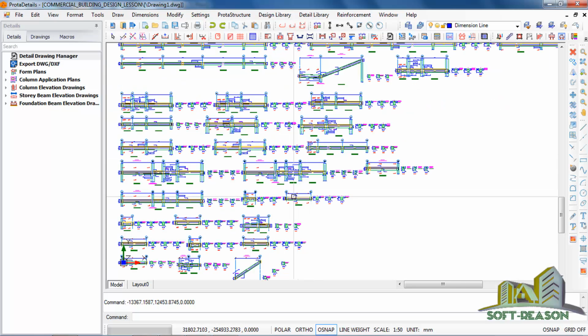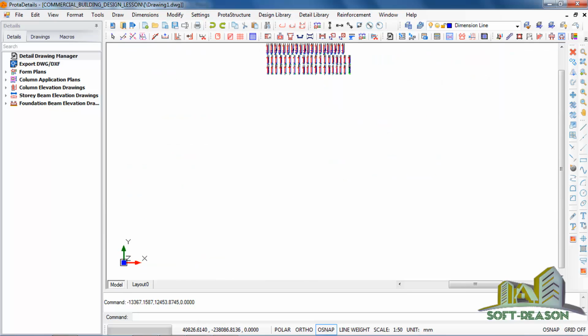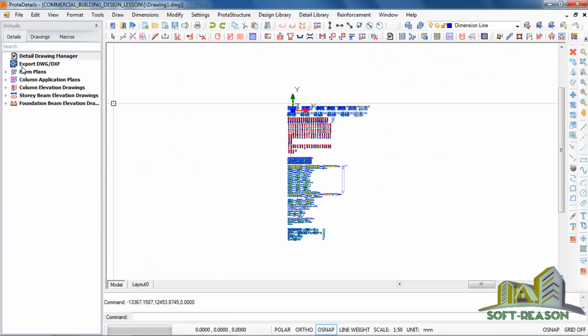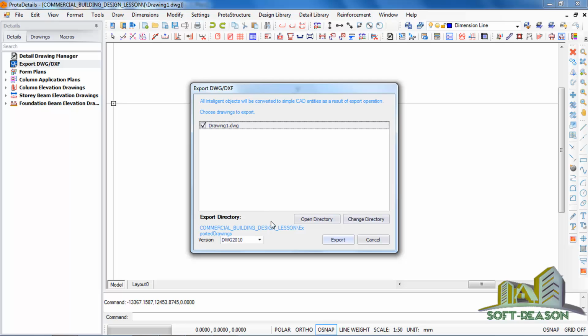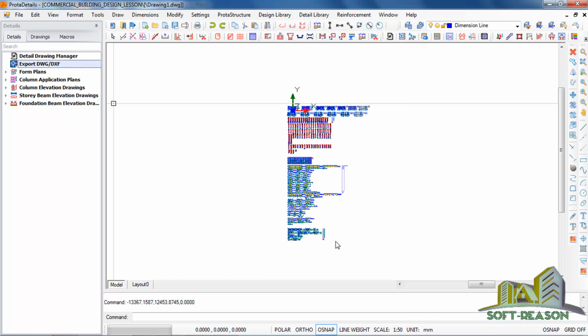So what you need to do now is come to this point, click on this point, right click, and then click on export. It will export this drawing in the form of an AutoCAD DWG version 2010, but I will save it in version 2007, so any version above 2007 can open it. So you click on export. You see that it is loading here. It will take some time to load at this bottom.